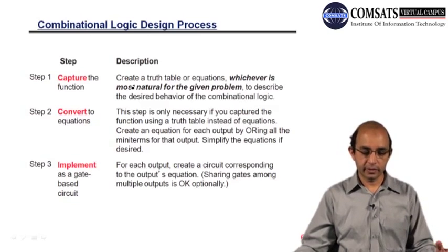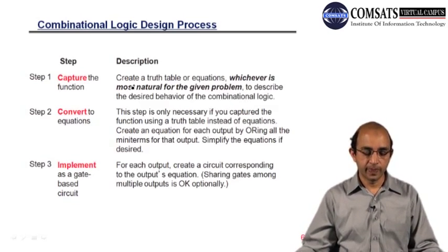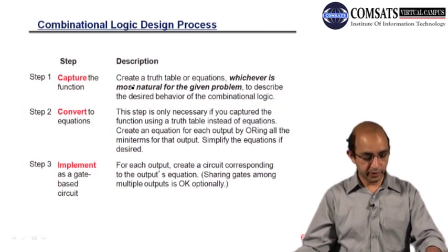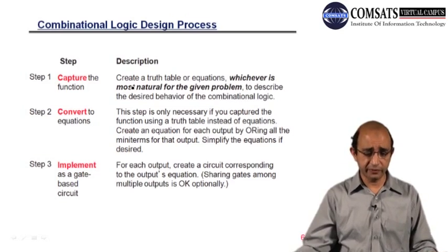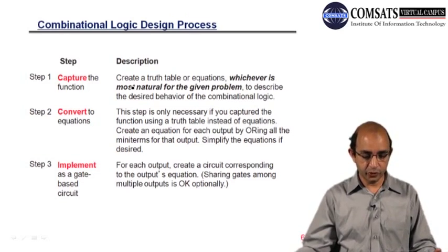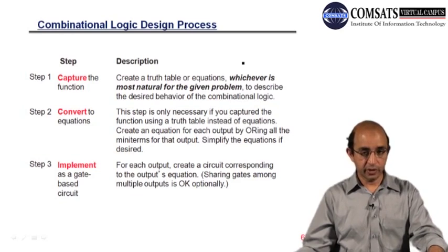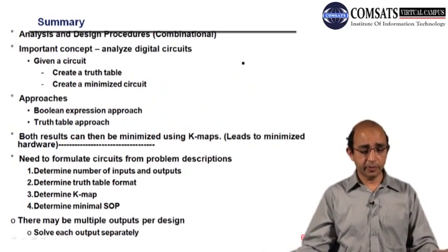Sometimes it's better to follow certain steps whenever you are performing the design process, right? So these are the steps, right? For example, first we have to realize the function, then we have to convert that function to equation, right? And then we have to implement the circuit, or we have to draw the circuit, right? So you can see that we have already gone through those different steps, right? So this is the summary, right?